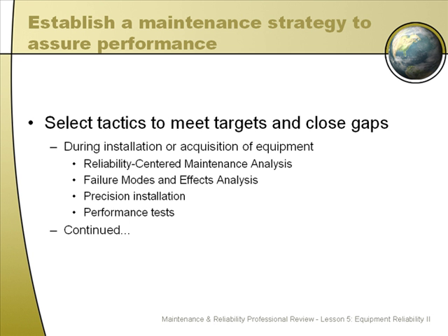Fourth, performance tests. Well, when you're going to do the installation, you want to make sure that you do certify that the machine can perform up to the standard or capacity that it was designed to do. And this kind of goes back to my discussion about having the vendors be qualified and also to have a performance clause in your contract. Because if the machine's not performing on day one, it's not likely to perform on day two any better than that.